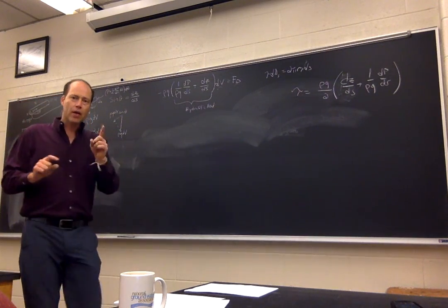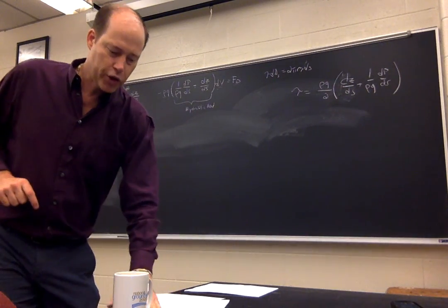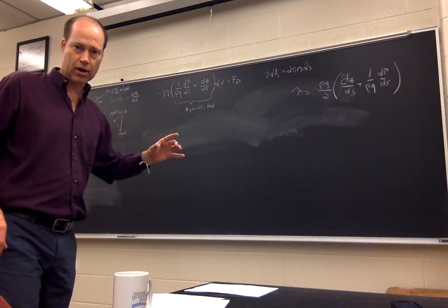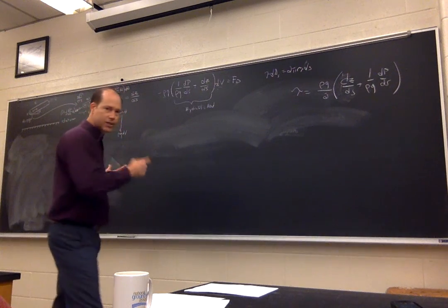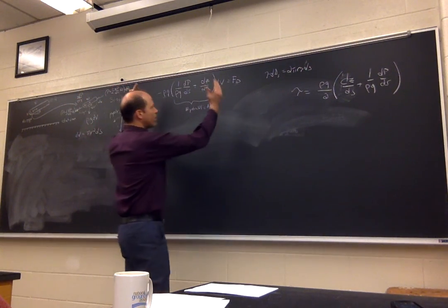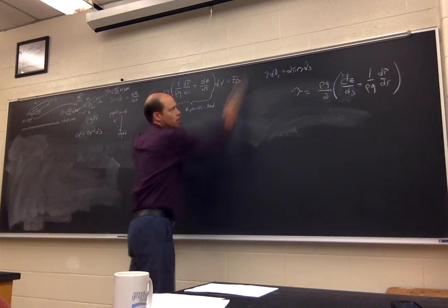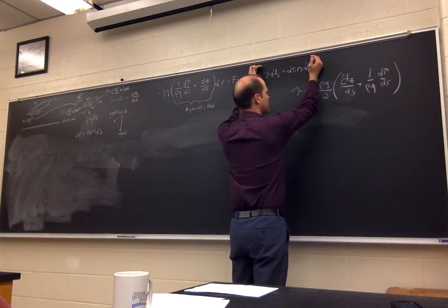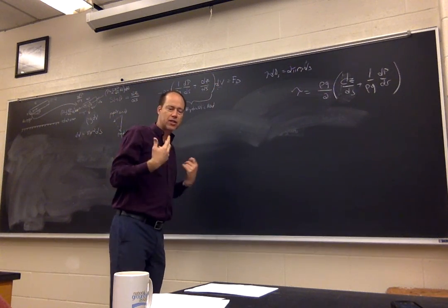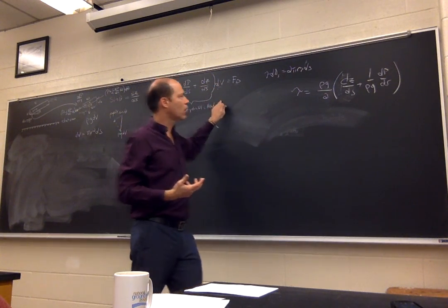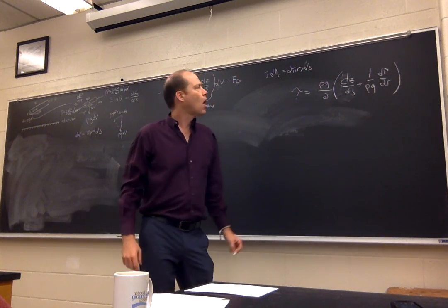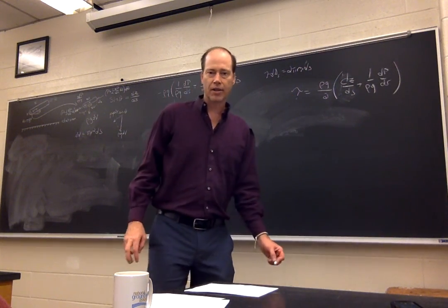Then we said if there's a change in pressure and a change in elevation across that, how do I sum up those forces to find the driving force and the frictional force? By equating those two, the sum of the forces must equal 0, I then solve for what the shear stress on that control volume must be.